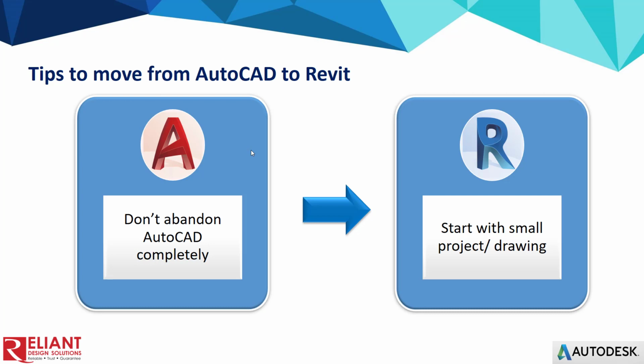And just one small tip for advanced AutoCAD users, for designers that want to start learning Revit. One thing to mention, for the execution of any command inside Revit, placing pipes for example, or connecting ducts for your HVAC system, you need to click the command on the ribbon under the tab, panel, and option bar too. You need to play with your command menu.